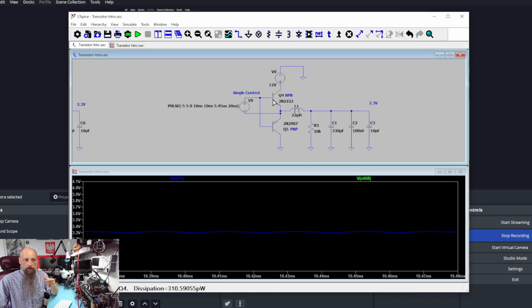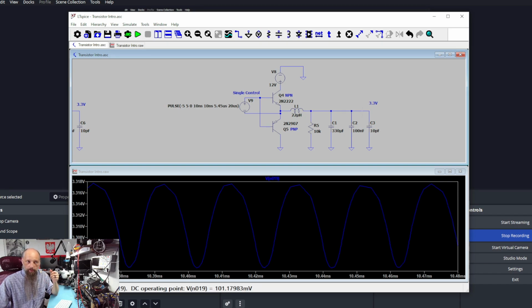Now, what's important to know over here is that if only one of these transistors catches a short, becomes a wire or low resistance resistor, it might not be immediately obvious. But if the high transistor catches short, if you connect 12 volts to the power supply, the 12 volts will go where 3.3 volts is expected, and it will fry the logic.